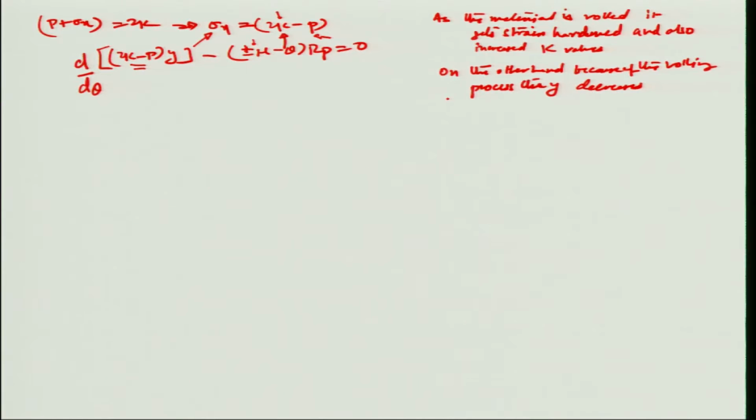So I can just assume a condition where, although it is only an approximation, if the strain hardening is not very huge, in that event it remains valid numerically that the Ky, that is with the increase in the strain hardening and the reduction in the sectional area, or the sectional thickness of the material, may remain a constant, and independent of the angle theta. Okay. So this is only an assumption.